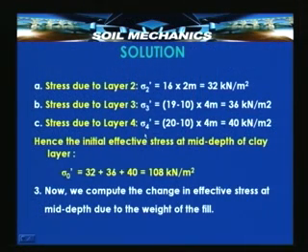So, now the stress at the mid depth of the clay layer due to the clay layer itself, the upper half of the clay layer, which is 4 meters in thickness, which has a unit weight of 20, is also saturated, and therefore, the buoyant unit weight applies here also. So, 20 minus 10 into 4 gives you 40 kilonewtons per meter square.